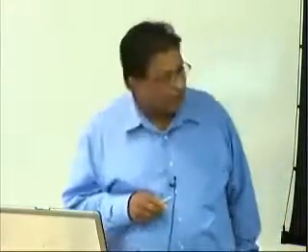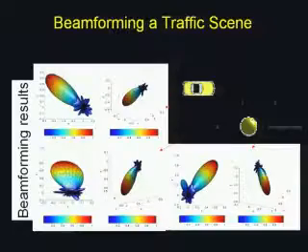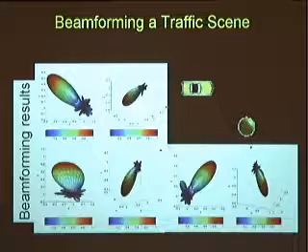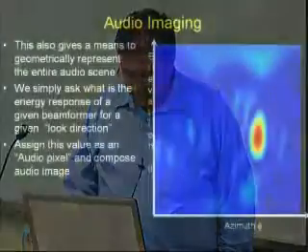Versus from the line, right. How much gain do you get? Oh, so ballpark. If you have 64 microphones, you can sort of get an 8th order beam pattern. So you can get sort of an n-fold, square root of the number of microphones, improvement in the gain of the microphone array using the sphere. We also use them to track traffic as it went along, pointing the array and taking it along.